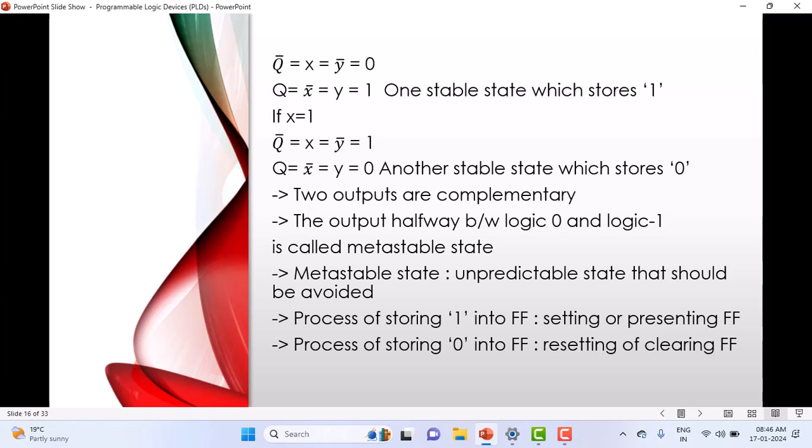That means you are seeing the basic bistable element in two states, which are 0 and 1. Just observe any one of these, don't see Q and Q bar simultaneously. Let's stick to Q. If you observe Q, look here, Q remains 1. And in the second, when I change the input from x is equal to 0 to x is equal to 1, Q becomes 0 here. That's how we have to assume the state, okay?